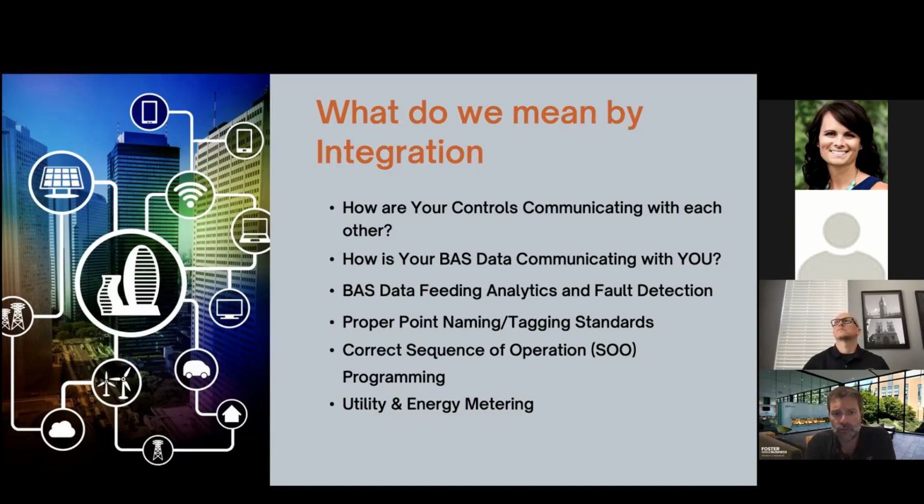Other systems, you might have a controls contractor installing the backbone, but your equipment might be factory controlled. So you might be going into a piece of equipment, an asset, but it's got all the controls taken care of internally. That gives you some visibility, but it doesn't necessarily give you the read and write capabilities, which makes it challenging. And then, as Brad mentioned, with the different types of systems, getting that data out of the proprietary ones can be done through their proprietary network. Sometimes you can try to get BACnet out of that.